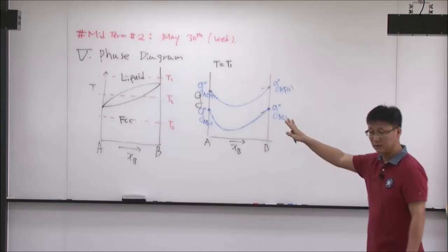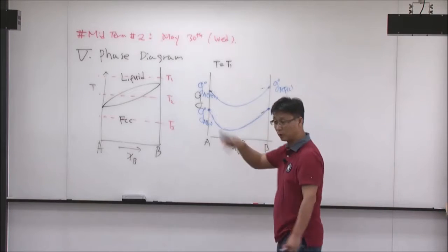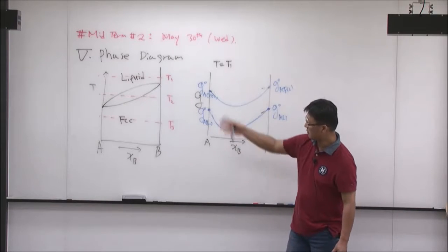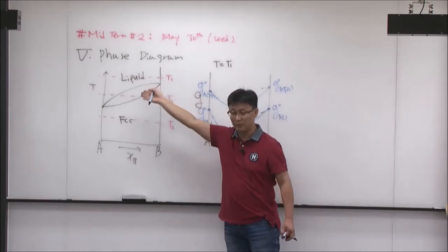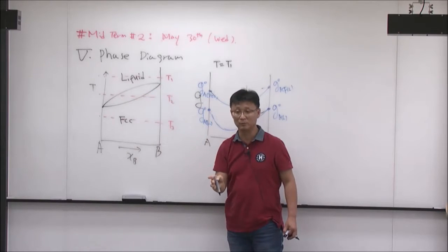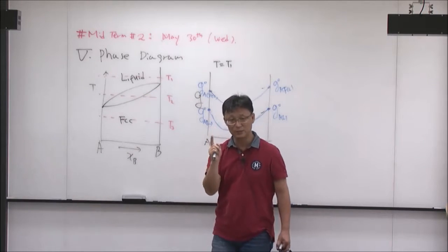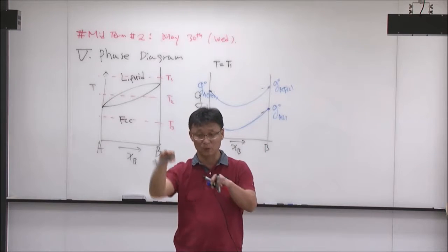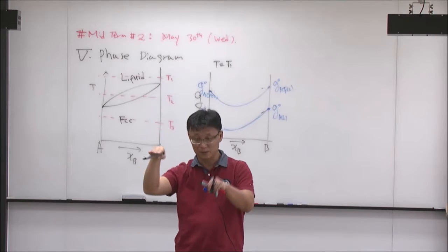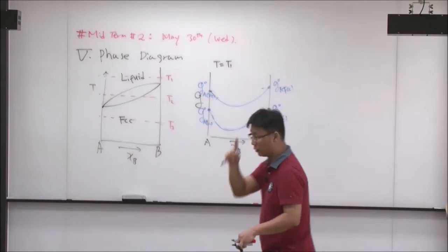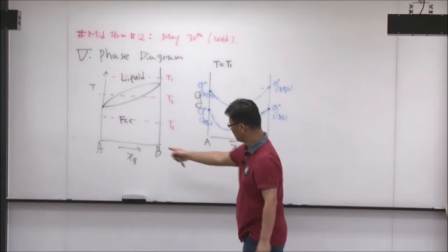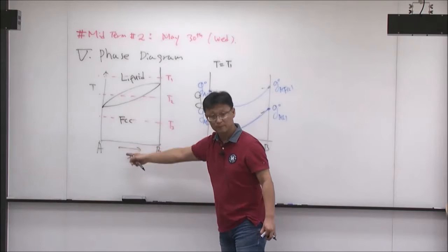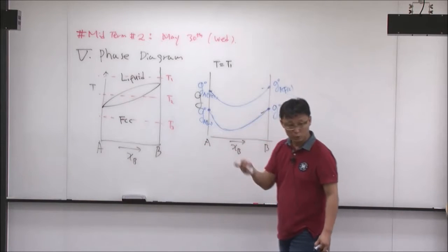It's pressure independent basically. Okay? So you don't have to worry about the pressure part. And then the next thing is the given temperature, because thermodynamic equilibrium is only obtained at a given temperature. You cannot have the equilibrium state of a system with two different temperatures. It's at one temperature. And then, what's the composition? Initial composition or overall composition.